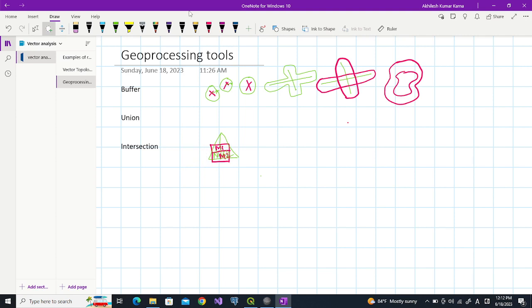then the area which is common to these will be created as the intersection, and it will have the attributes from both these layers. Let us see what the output is in our QGIS. In the case of union, not only the common area but also the area not common to both these polygons, like this area, will be in the output, but it will have a null value for one of the layers. Let us see in the QGIS.